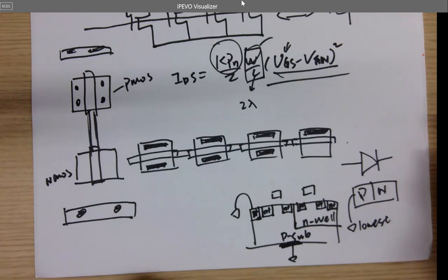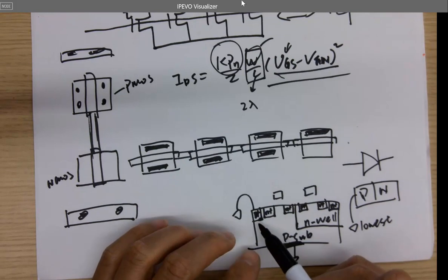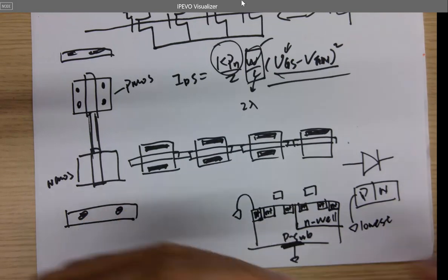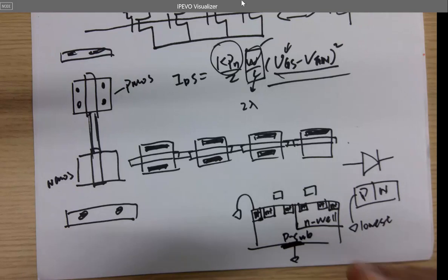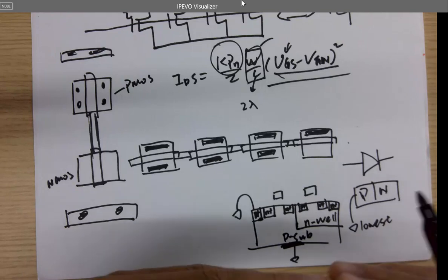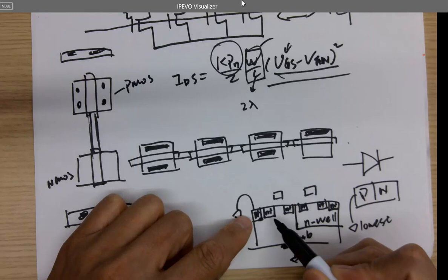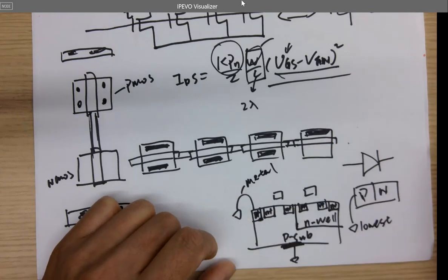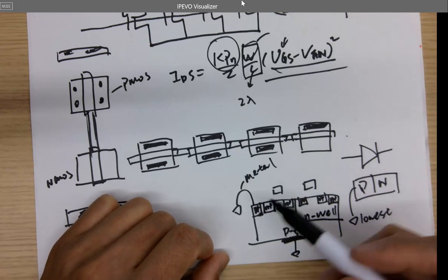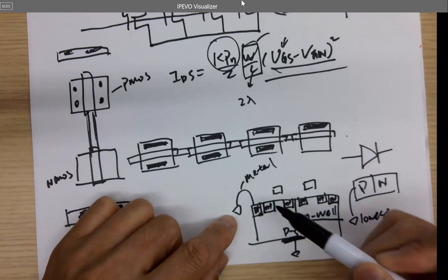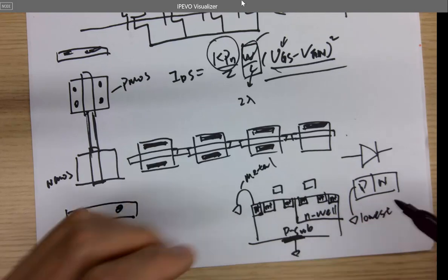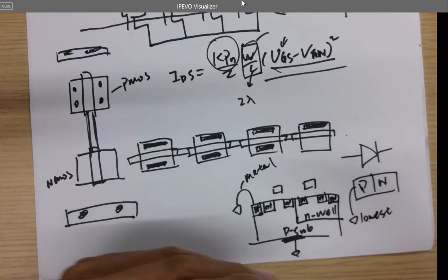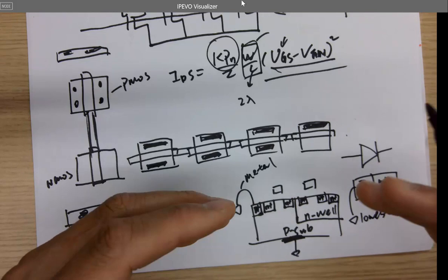So you have to have some intermediate material in the middle, so you can connect. This is metal, right? So P plus allows... Oh, you are talking about why not directly using a metal to the P? Because the P plus is heavily doped, more concentrated, more conductive.